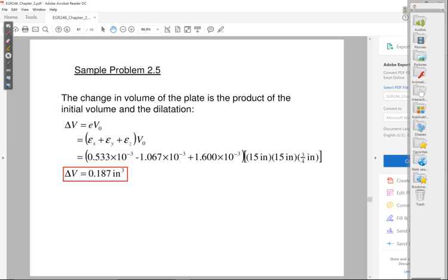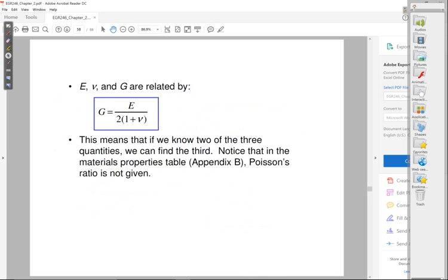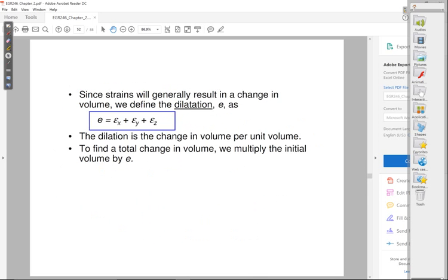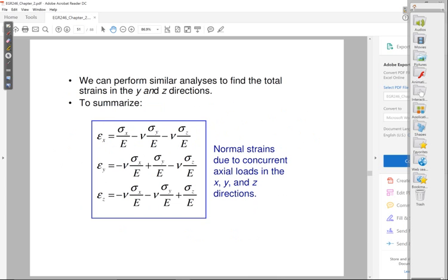All right, let's go back to the generalized Hooke's law for a second. And I just want to discuss very briefly this idea about rubber being incompressible or having a Poisson's ratio of 0.5. Okay? So if we apply generalized Hooke's law to a material with Poisson's ratio of 0.5, look what happens.